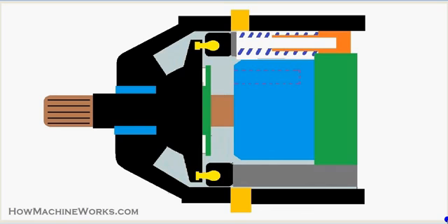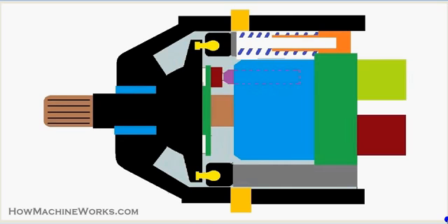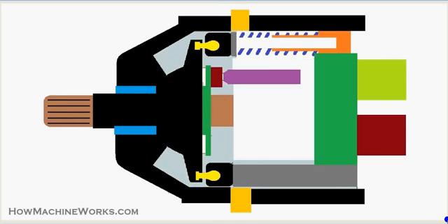So that's the position where the pistons are arranged. You can see when the cylinder block rotates, the pistons also rotate together with the cylinder block, sliding over the swash plate. So let's see. So that's the piston being arranged inside. The dotted mark shows how they are arranged inside the cylinder block. So that's our inlet and outlet, as I have already explained. So you can see the piston, the inside view, how the pistons are placed inside the cylinder block.